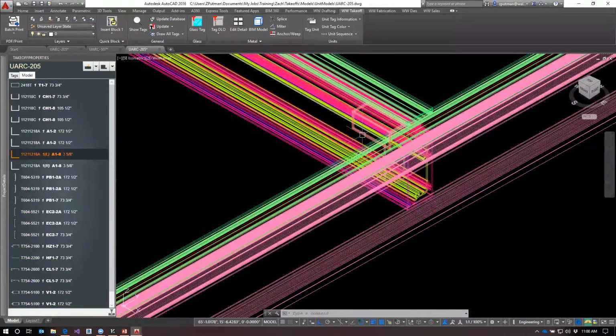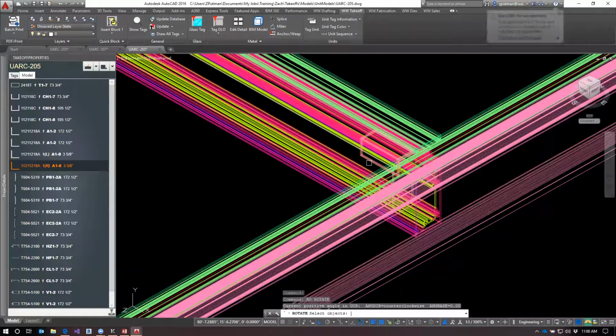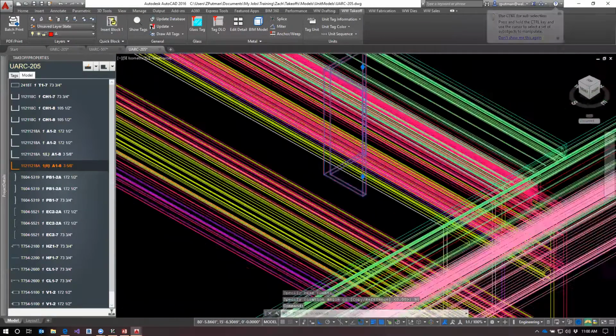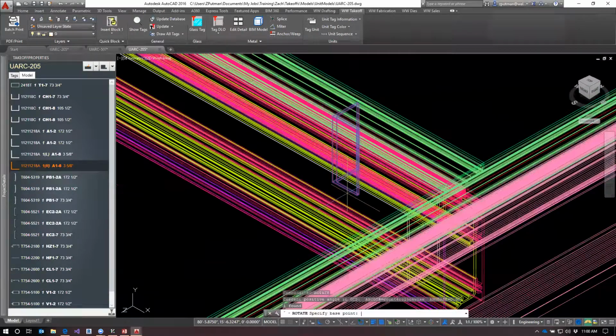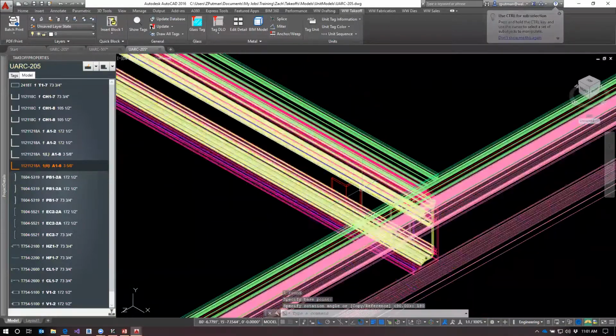Let's do this here. I want to UCX. So we have some UCS commands that abbreviate how you rotate it around. UCX will just rotate it around the x-axis 90 degrees. Then I can use the normal rotate command, rotate that 90 degrees. Of course, I should have done -90. Rotate again. 180 now. Now that's in the right place.